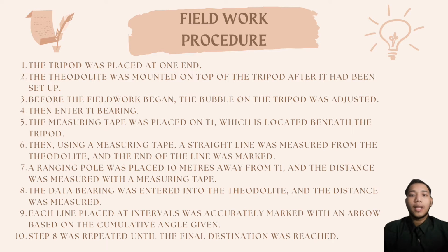And then for my last part, I will explain about the fieldwork procedure. First, the tripod was placed at one end, and then the theodolite was mounted on top of the tripod after it had been set up. Third, before the fieldwork began, the bubble on the tripod was adjusted, then T1 bearing was entered, and then the measuring tape was placed on T1, which is located beneath the tripod.